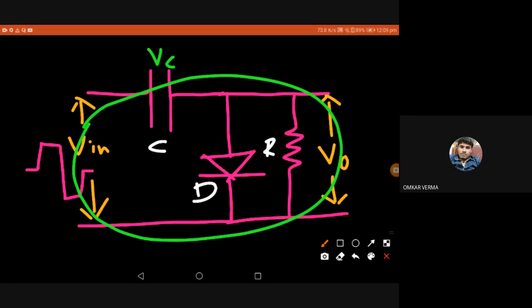That is a non-ideal thing. You should understand the capacitor has a discharge option, but we are not allowing the capacitor to discharge. For example, there's a time constant like 5 time constants, 3 time constants. What time constant? Tau, the time constant RC, right? The time constant RC decides the time required for the capacitor to charge and discharge to a particular level, maybe 63%, 90%, etc. So if we keep it larger, the capacitor will retain the voltage, so that we'll get a perfect output square wave, right?